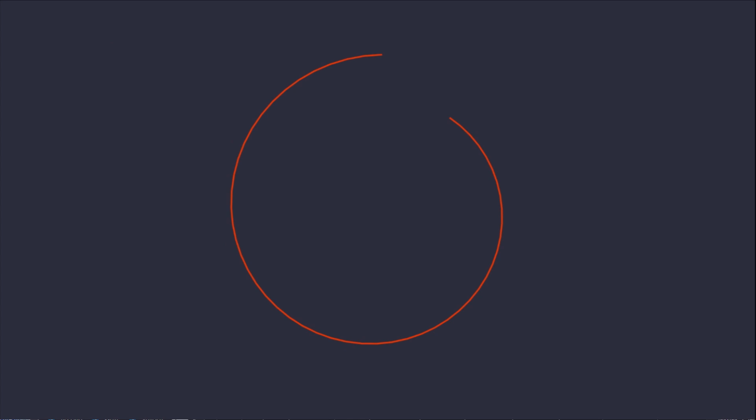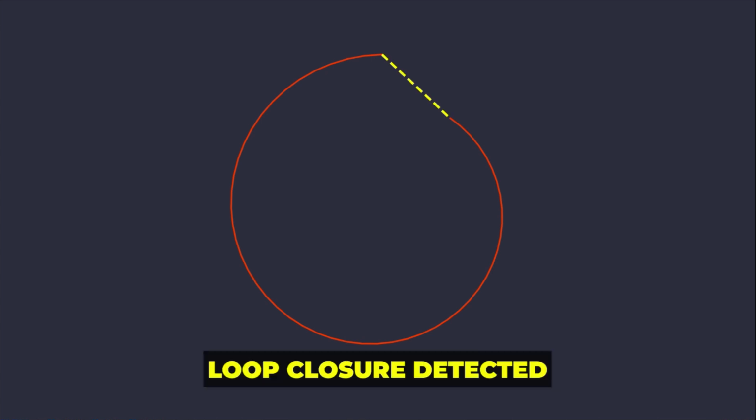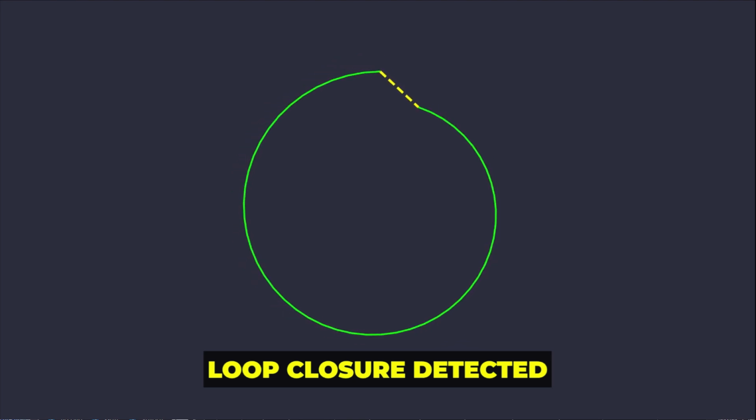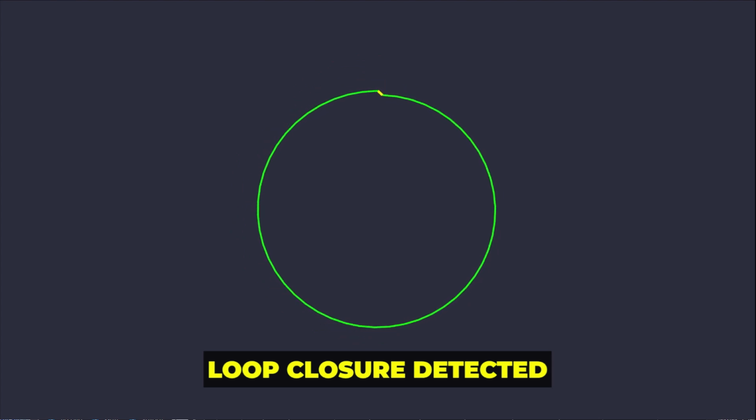Without loop closure, the accumulated error from odometry constraints causes the estimated trajectory to drift significantly over long distances, resulting in globally inconsistent maps. Loop closure is the process of recognizing that the robot has returned to a previously visited location. This recognition generates a non-local constraint edge in the graph, connecting two temporally distant pose nodes. This new edge introduces a powerful constraint that forces the intervening trajectory segment to conform to the known relative transformation between the start and end points of the loop. This mechanism is essential for achieving metric consistency and bounding the growth of positional uncertainty across the entire map.